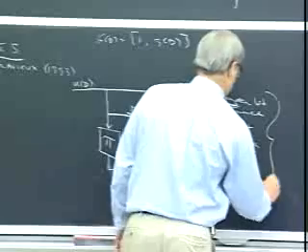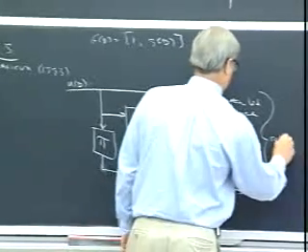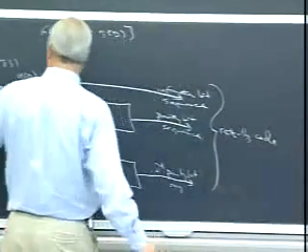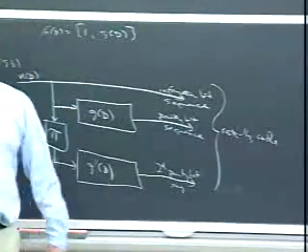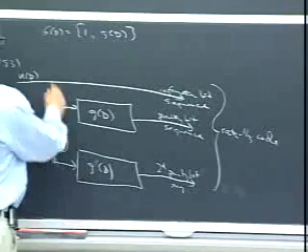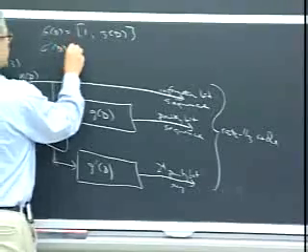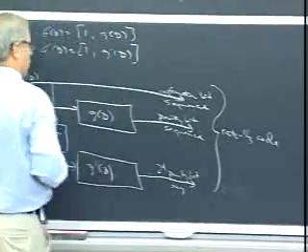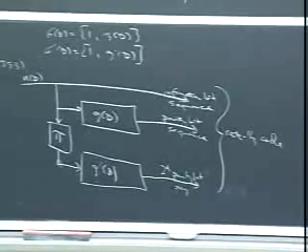And this all together I will call a rate 1/3 code. For every one information bit in, there are 3 bits out. Same sense as convolutional. All right. So the second code, G prime of D, is 1 G prime of D.